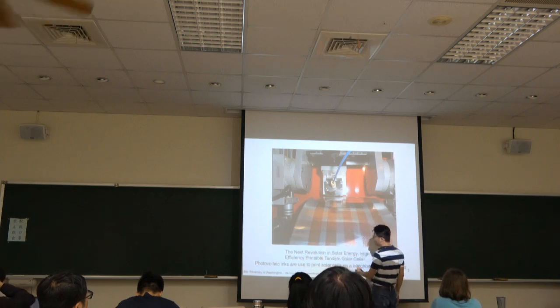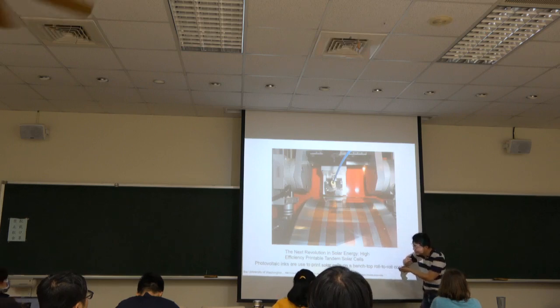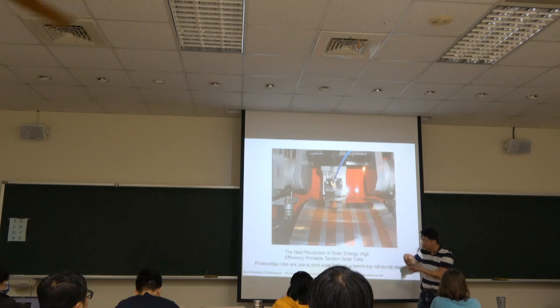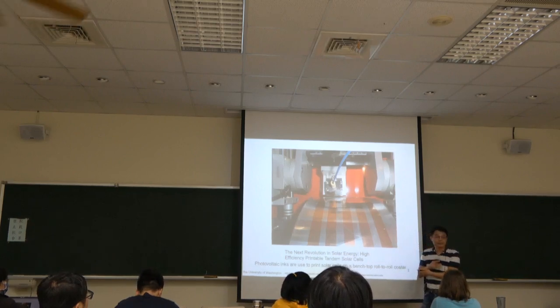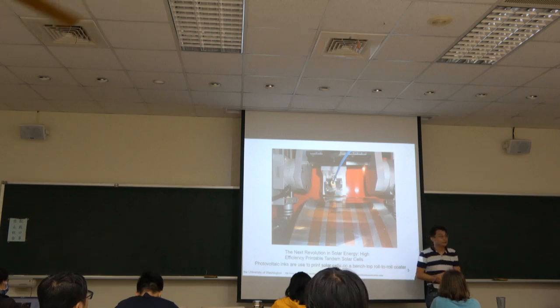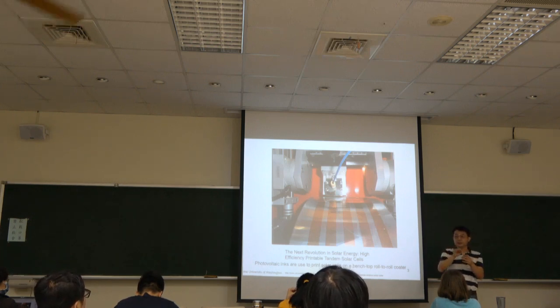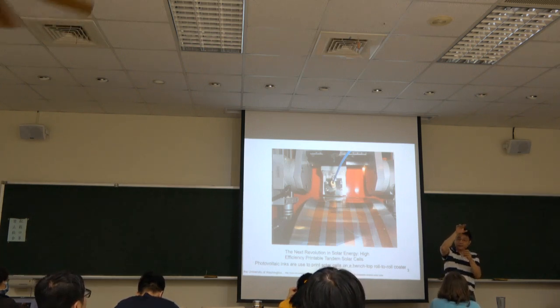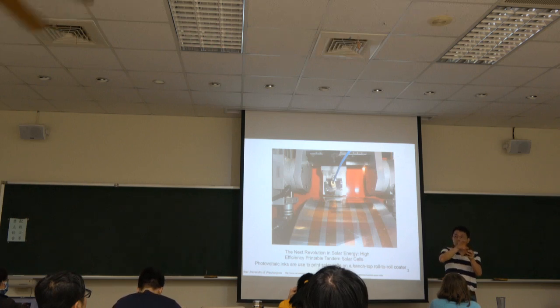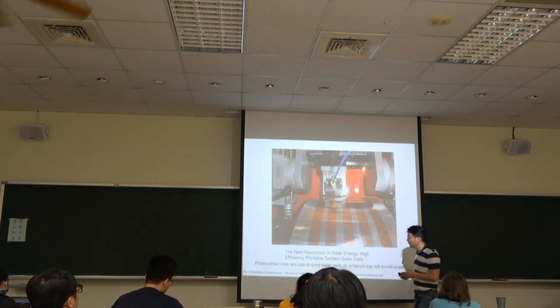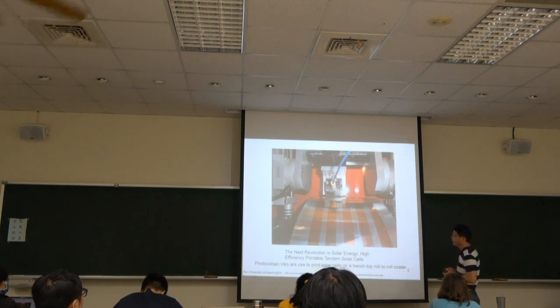But for the tandem structure, because you can deposit layer by layer, it looks like a thin solar cell. Therefore, we can create a multi-junction solar cell. The top junction is cell 1, the middle junction is cell 2, and the bottom junction is cell 3, which can absorb different wavelengths of the light radiation, right? So this is an advantage.